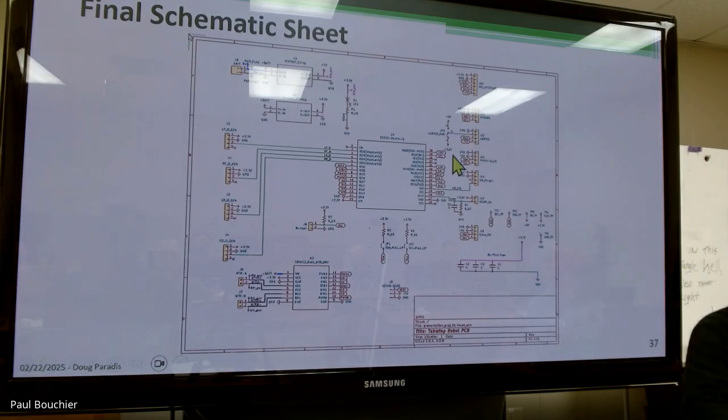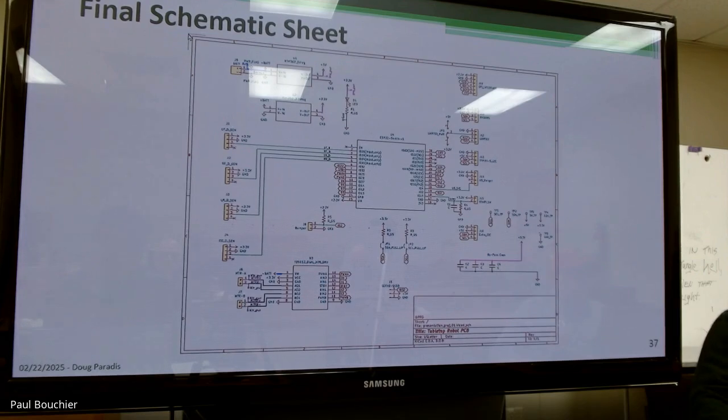That jumper sets the signal level. Let's say you wanted to use it for a 3.3 part. You would normally leave it on 3.3. But if you were doing it for a TF Mini-S in UART mode, you would move it over to 5.